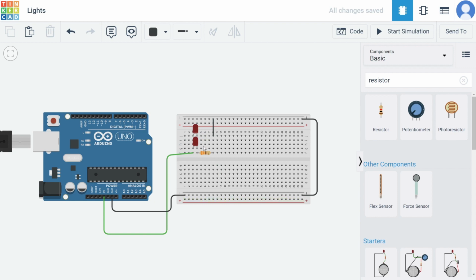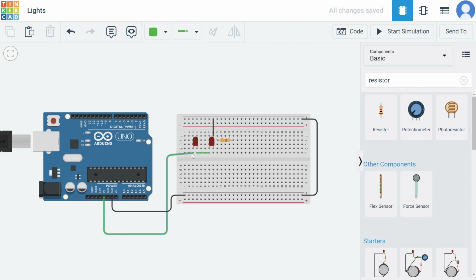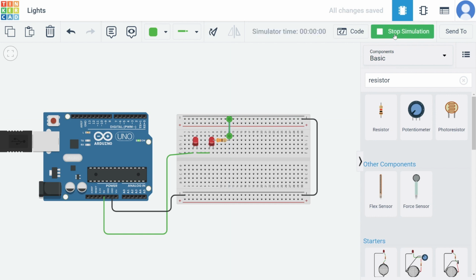This will not work if you daisy chain them together, like this. I'll just show you quickly. If you have the circuit go through one and then through another one and then through a resistor and then through the ground up here, they'll still go on, but they'll get half the voltage because the 5 volts is split over the 2. And if you did it with 3 or 4, very quickly they just won't turn on at all.